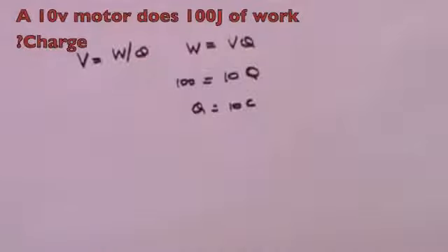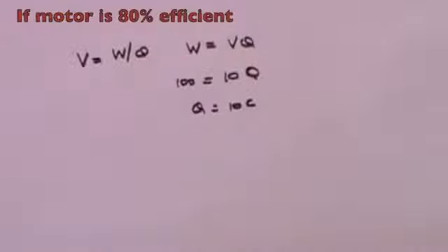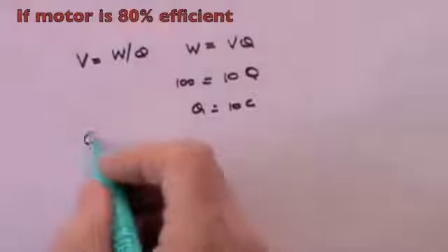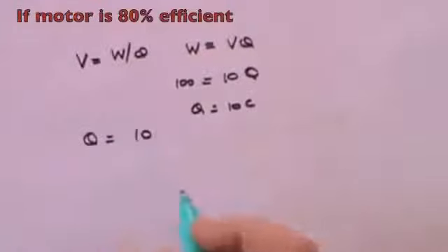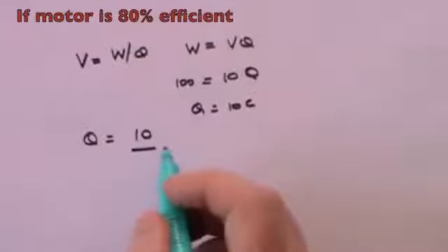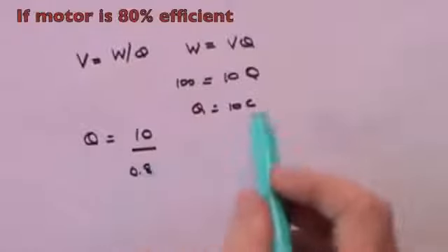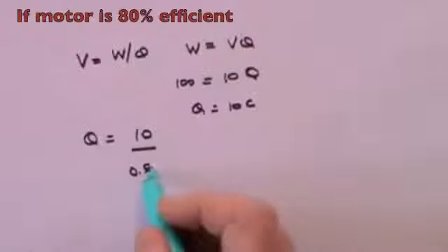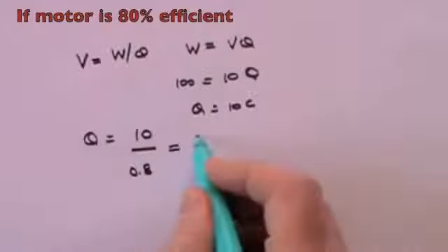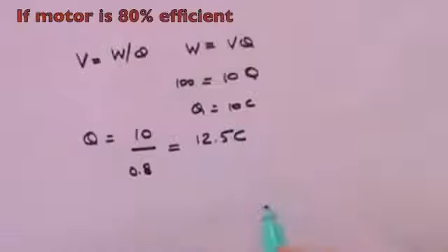Now the second part of the question is, suppose that motor engine is only 80% efficient. What charge do you now need? And the answer is that the charge will be the 10 coulombs, which was the answer we got here, divided by 0.8 because it's only 80% efficient. And that gives you 12.5 coulombs. You need a higher charge if there's a lower efficiency because some of the work is wasted. That's the whole point about efficiency. If it's less than 100%, you lose energy. And consequently, you needed a high...